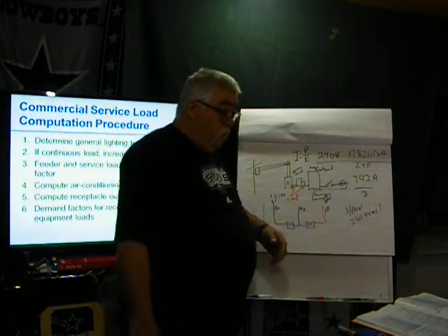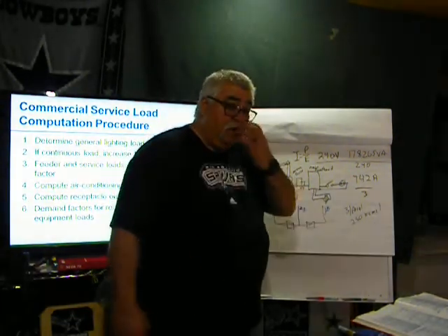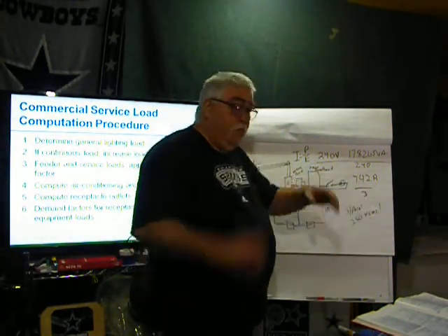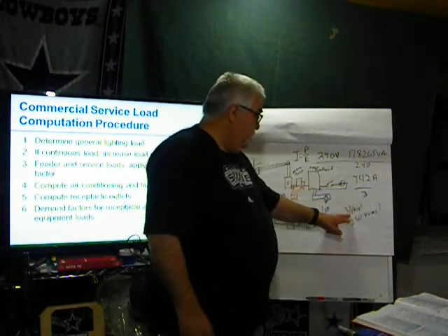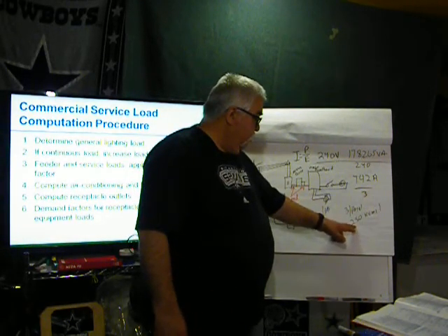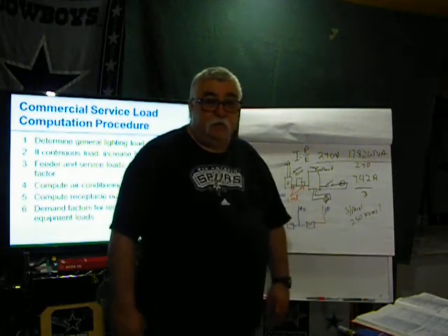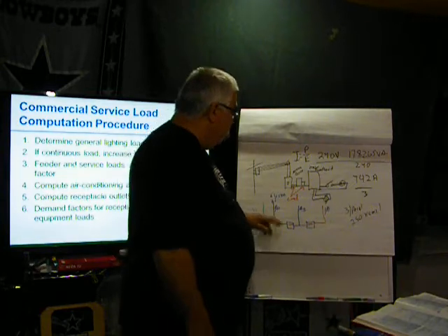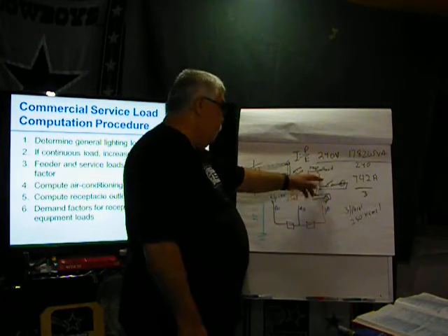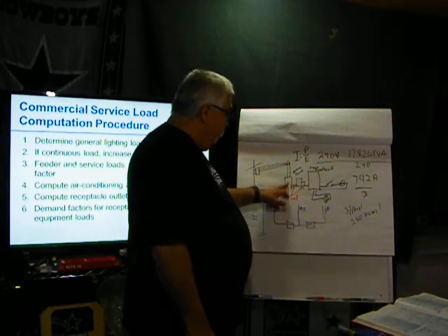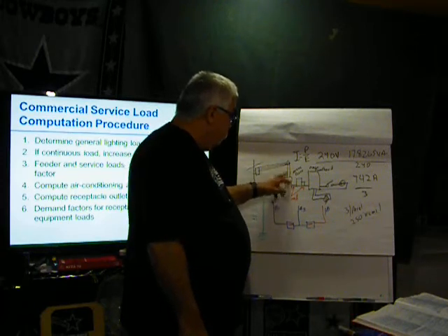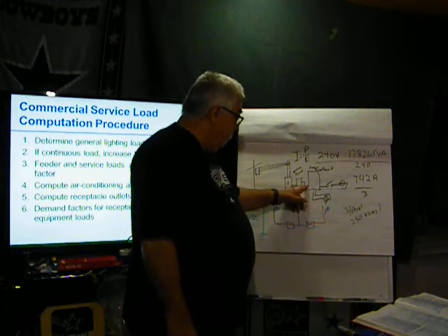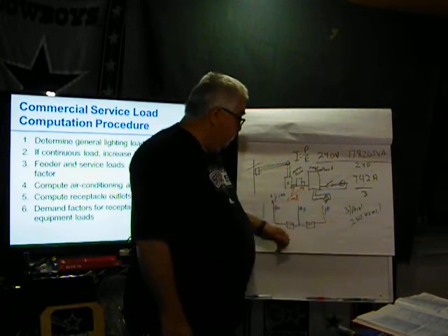Okay, I couldn't find a wire in the table, but I go back to 310.15(B)(16) and I look, and let's say I want to run 3 parallel runs, so I divide it by 3. So I would have 3 parallel runs at 250 kcmil in each parallel run. So that's where we're talking about the parallel runs. So again, your feeder would be between, say, the main panel and your service meter, even going up to your meter size accordingly. So this is your feeder right here, going from the service disconnect to the panel.